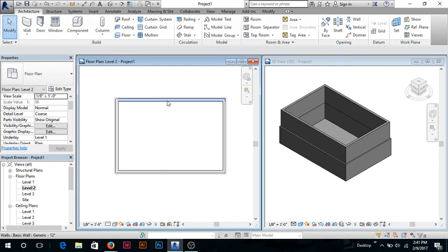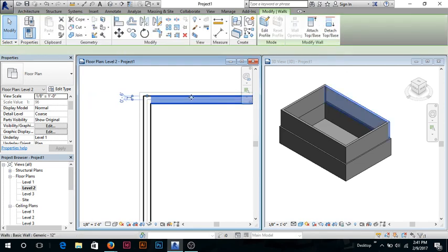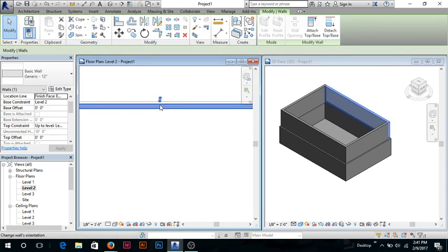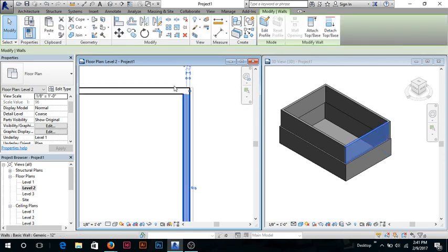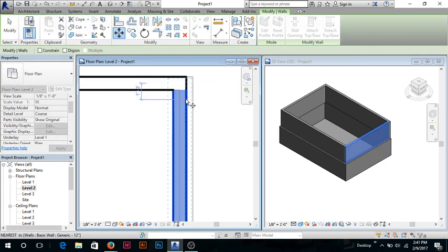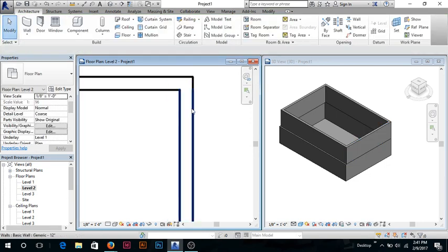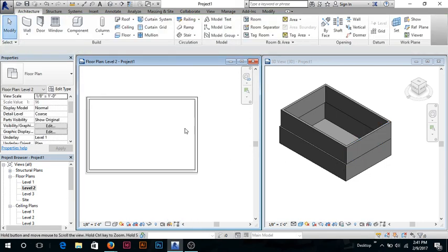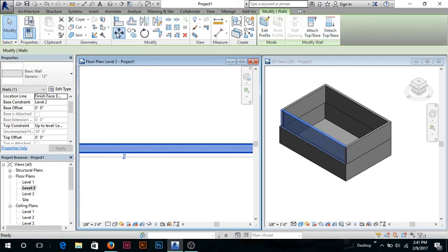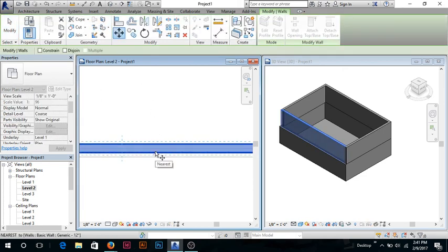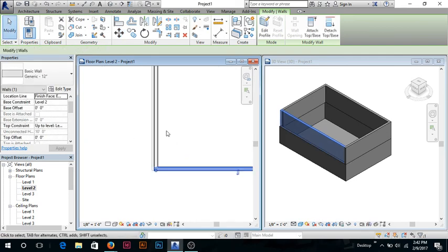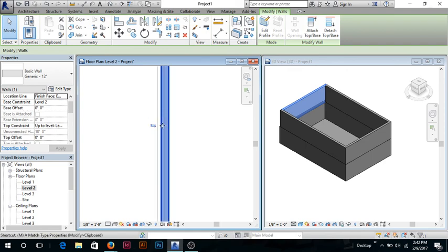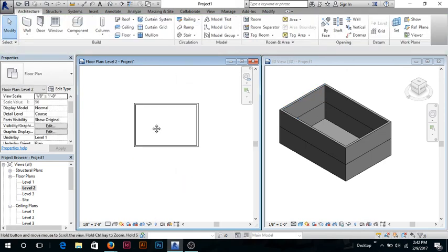Now there's a small issue where I went to the center, which is kind of annoying. You can easily just click on a wall, in this case, and just drag it up to snap properly to where you want it. Or you can just click on it, press the move button right here, and do click, click. Look at that, nice and flush over here on the outside. Again, I'm going to click on this button, the move button. Hotkey for that is M as in Mary, and then V as in Victor. Click, and then click. There we go. So here is our second floor.